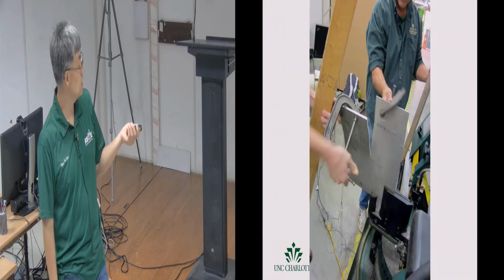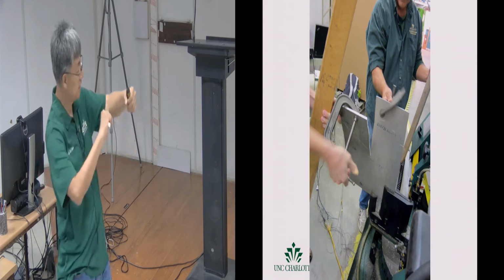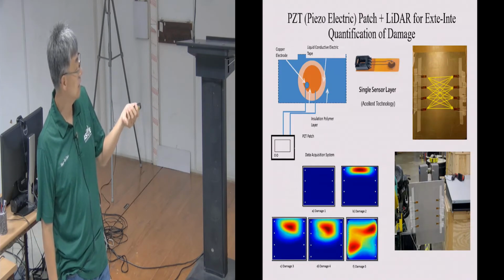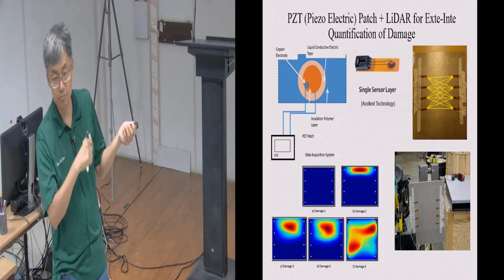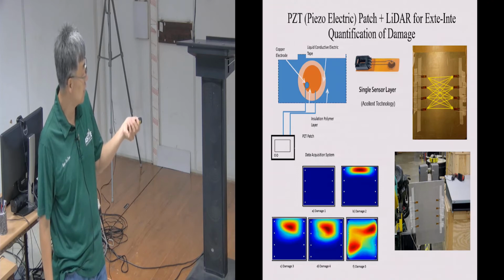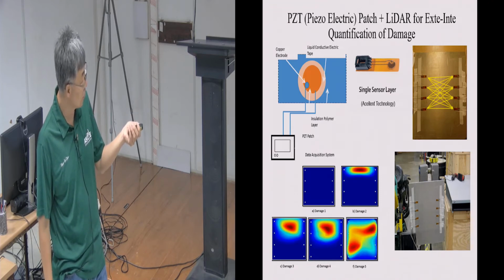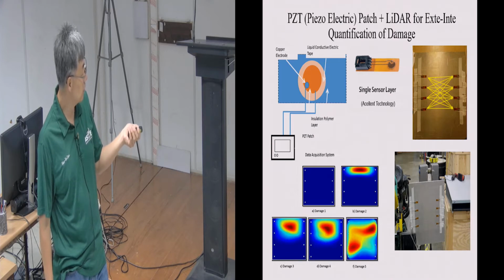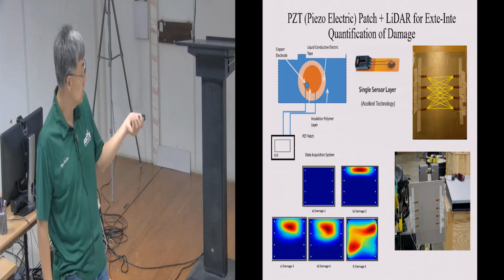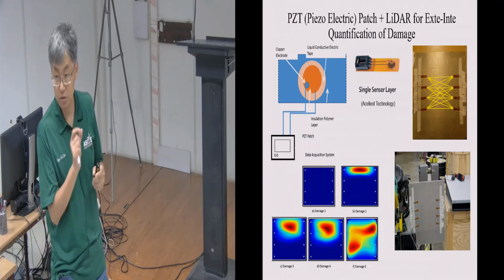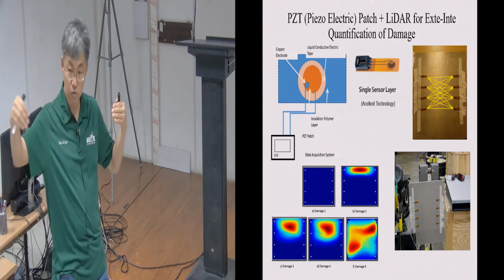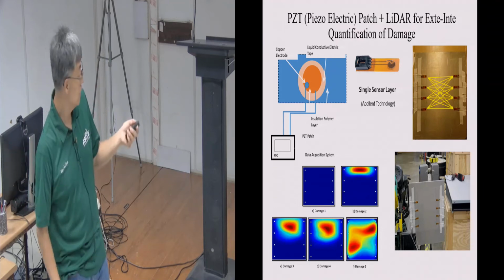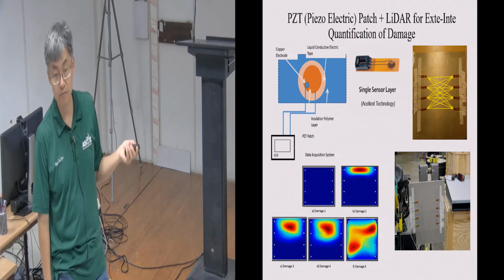Okay. And then after the test, we force the plate to have plastic deformation. Okay, aluminum plate. And so as a result, you can see the waves traveling, these are artificial. We just demonstrate. And then you get this kind of result. You literally see as the crack, the saw cut, goes through, the red zone slowly going down the plate. And then at the point where we start making plastic deformation, you see the stress concentration actually go away from the plastic zone. Okay, because the forcing on the two ends, the large deformation, the bending, will result in the stress. So what that tells me is all this stress is relative, okay.